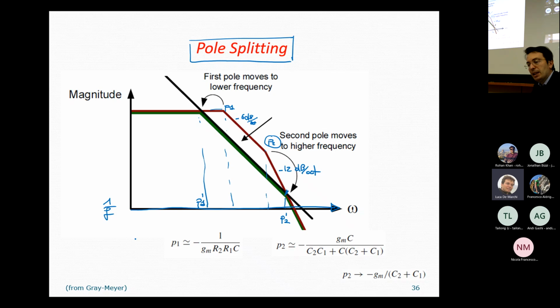Okay, so typically in this combination, I5 over the compensation capacitance is the smallest value, and therefore the slew rate for positive step function is equal to I5 over the compensation capacitance.